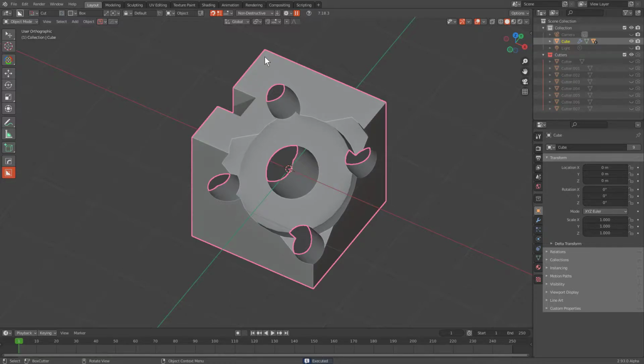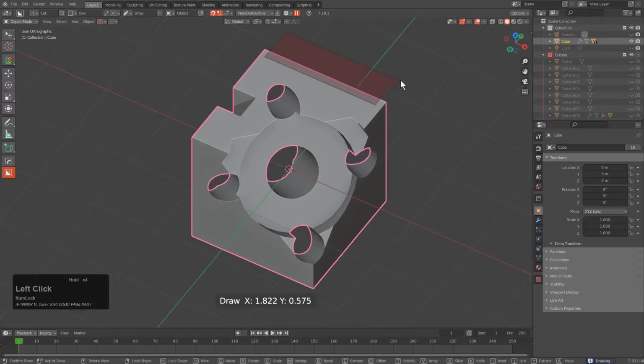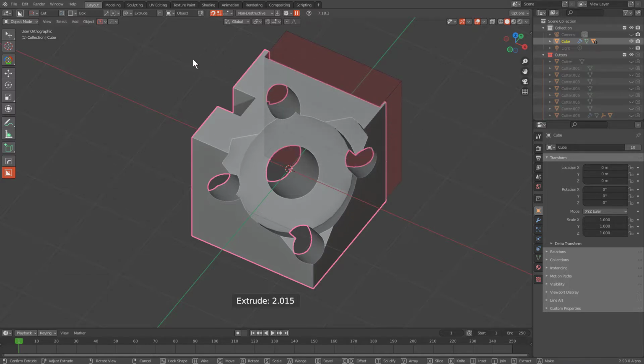But I'm just letting you know that improvements have been made in this regard for this particular update to make view extrusion as easy to toggle between as possible. And you can just press Alt to jump back to System A, and you can even tap Alt again to switch back to System B in the event that you miss it and want to just control the amount of extrusion that you're doing by the distance that you're moving your mouse.